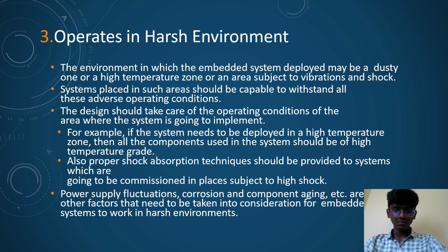For example, if the system needs to be deployed in a higher temperature zone, then all the components used in the system should be of high temperature grade. Also, proper shock absorption techniques should be provided to systems which are going to be commissioned in places subject to high shock. Power supply fluctuations, corrosion, and component aging, etc., are the other factors that need to be taken into consideration for an embedded system to work in harsh environments.